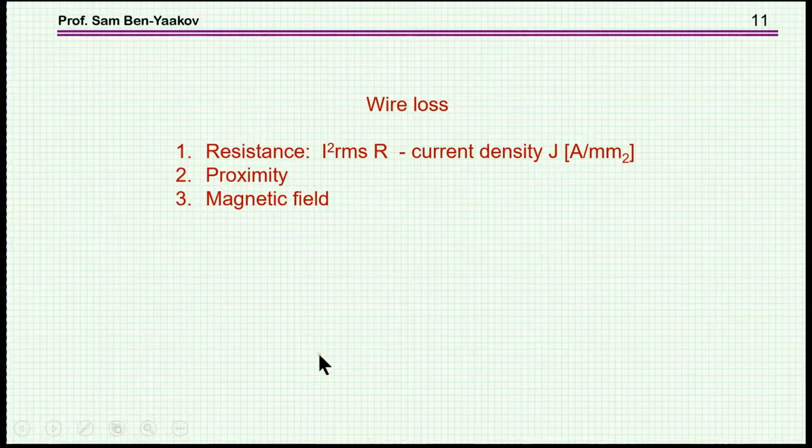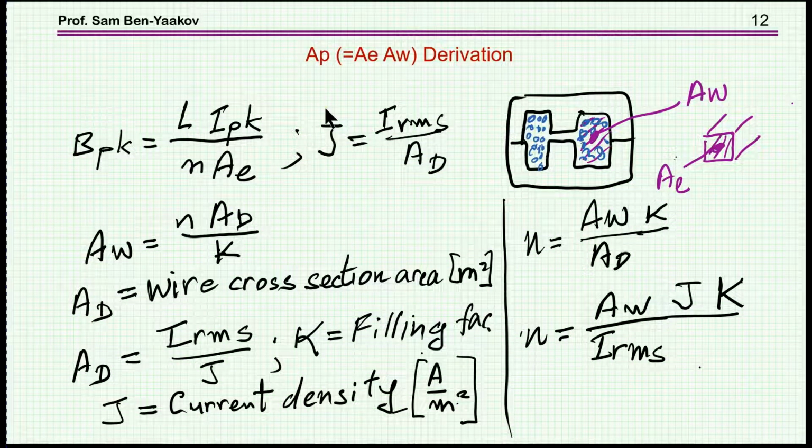in this tutorial. So we come now to the very important parameter, AP, the area product, which is the product of the cross-section area of the core times the window area, or the winding area, of the core. Our objective is to select a core such that the losses will be as we decided, and the maximum magnetic flux density will not be over the limit, and then we would like to fill up this area so as to optimize the design. So we have seen this relationship already.